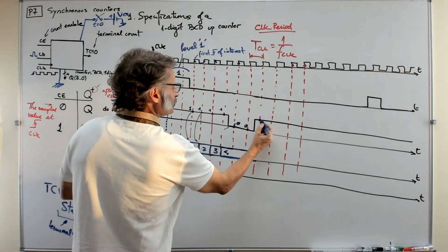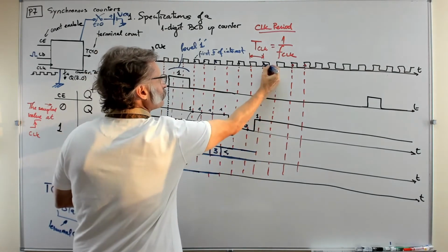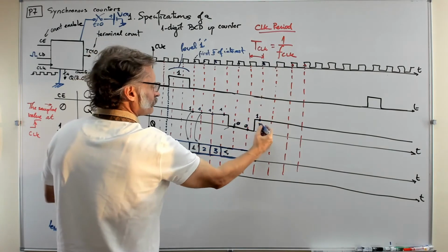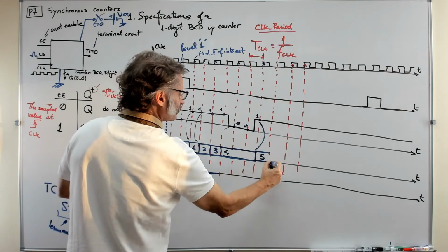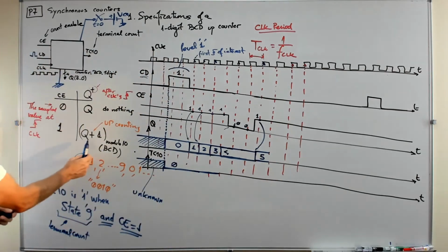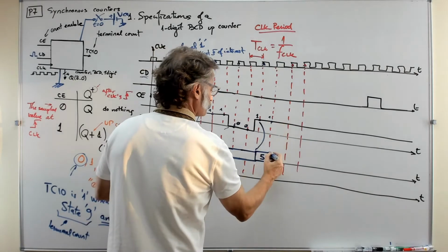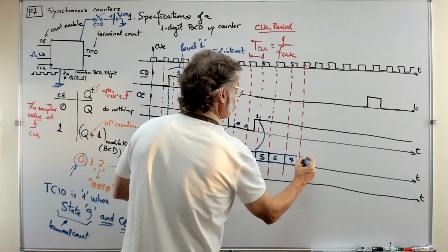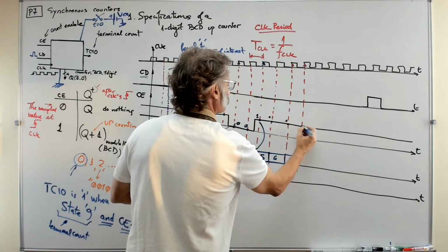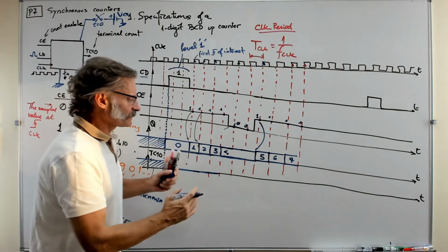But now you see, it went high before the arriving of the rising edge of the clock, but now you sample a 1, so now again you have the possibility to switch to a 5. The current state plus 1, this is the idea of a counter. And then again another 1, so you switch to a 6, and then you switch to a 7, because you are sampling another 1. You see, this is the way, take it easy, right? One clock at a time all the time.